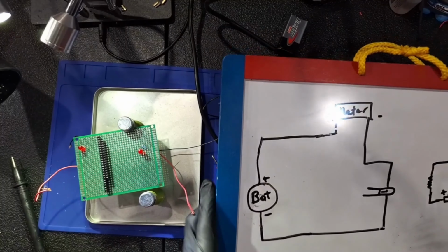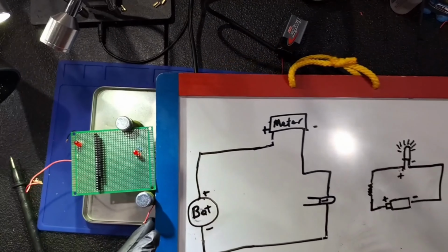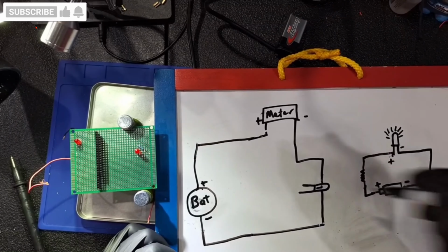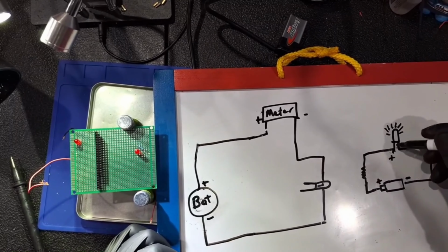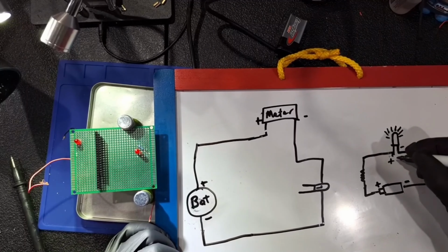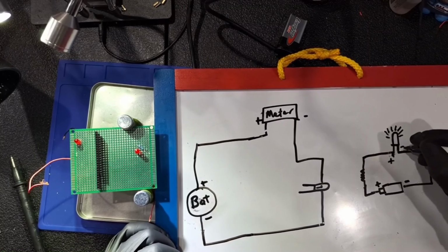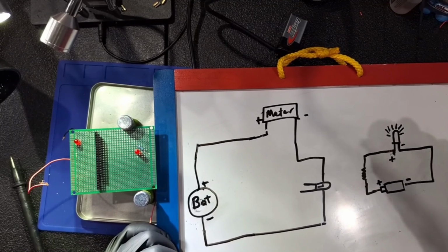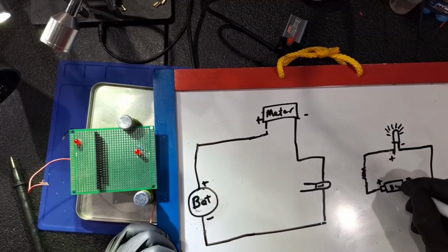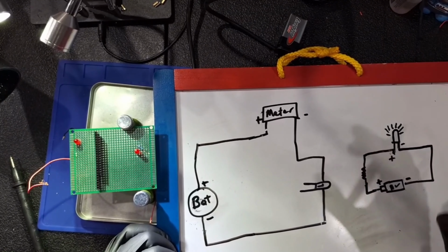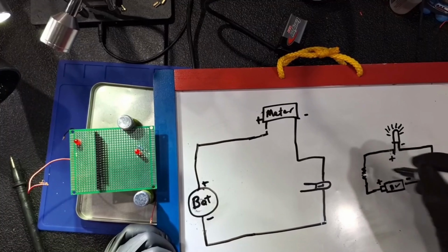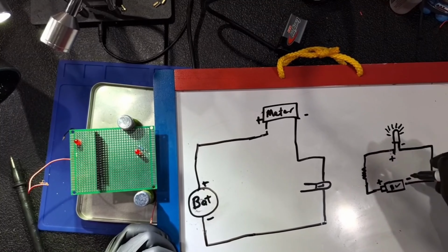So I have two drawings on this whiteboard. I have one with the multimeter breaking the circuit, on the left, that's a bigger image, and the one on the right is the current simple circuit that I have, with the LED connecting directly with a wire to the battery. So right now I have the negative side and the positive side, and on the left side I have a resistor and a 9-volt battery. The 9 volt with a resistor just to prevent the LED from burning up. So that's why I have that there.